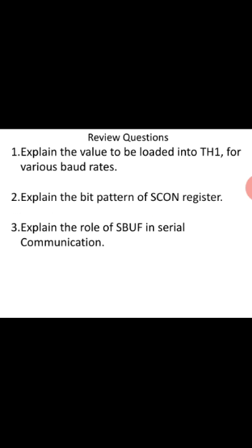Here are some review questions. Explain the value to be loaded into TH1 for various baud rates. For various baud rates, what are the TH1 values? You should be calculating it, as we already discussed. Explain the bit pattern of the SCON register: SM0, SM1, SM2, REN, TB8, RB8, TI, RI should be explained. And explain the role of SBUF. What is the role of SBUF? You have to explain why it is used, which we already discussed in the session.